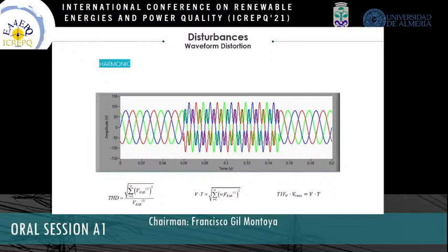A sinusoidal signal loses the proper shape of a sine wave when it becomes distorted with harmonics but remains a periodic signal. The appearance of harmonics is due to the high usage of nonlinear devices and nonlinear loads in power systems. As you can see, the harmonics happen between 0.06 seconds and 0.15 seconds.